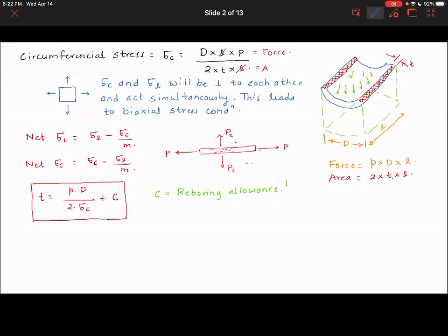The piston and cylinder assembly starts wearing out. The piston reciprocating inside the cylinder starts pitting the cylinder surface. So you will see small, teeny tiny scratches. Initially those scratches may not be visible, but over a period of time they deepen. Or sometimes there are impurities in the fuel that may not be visible to us, but they get impinged on the cylinder surface and scratch it.